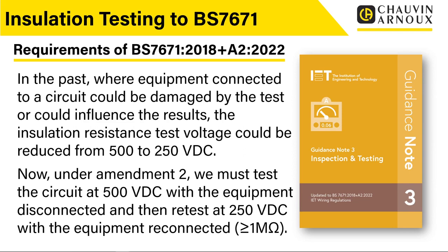So I think there will be arguments that people will use in this when it comes down to electrical installation condition reports, and there may be limitations, or there may be, you know, comments that people make on the test to actually say that they weren't able to carry out that test with all the equipment disconnected first. But again, you know, there is a change in the regulations, and it has been done for the right reasons, really, to make sure that people are actually testing at the highest voltage they can, rather than, I think what was happening was people were just choosing, right, I'm just going to test everything at 250 volts because why wouldn't I? You know, it's easier, I'll just do it at 250 volts and that was it.